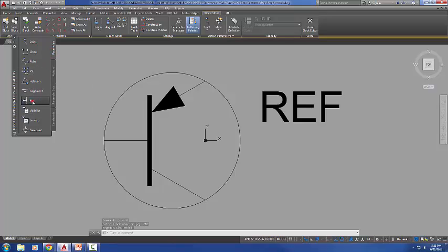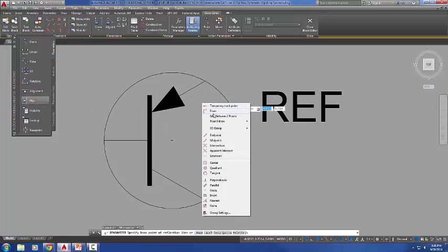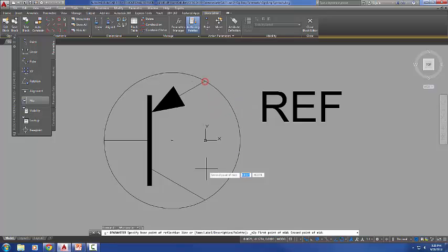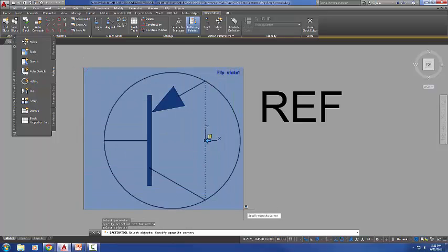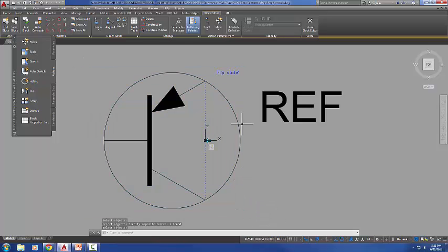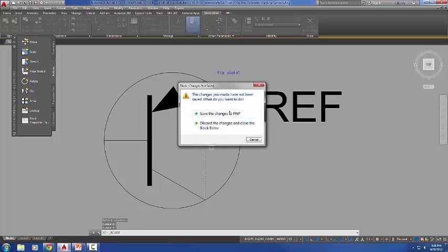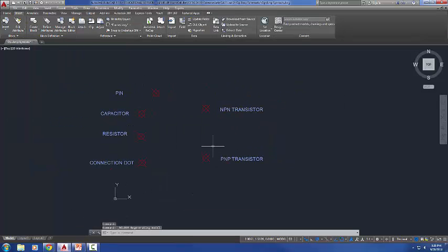So go to parameters which is first, the default UCS. We'll do the flip parameter mid between 2 points. Go to actions, UCS, flip action, select the parameter, Views, select the objects, close and save. So I've got all of my blocks made.